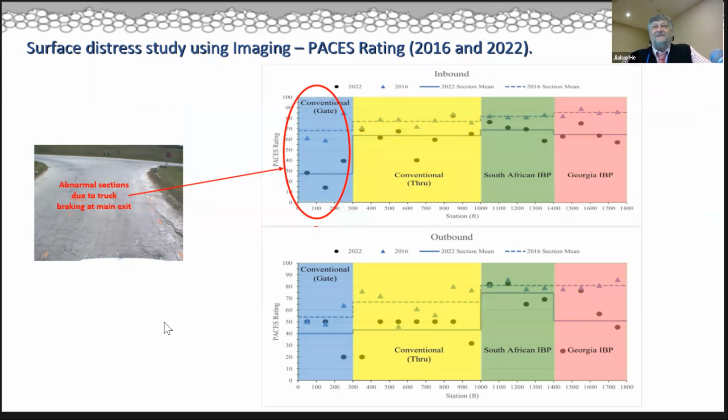We have a test section here, and other than the falling weight deflectometer that was put in, that was collected 6 years after it was first put in, we have no baseline data on surface distress, on rutting. We need to get a data set. And so as soon as I got involved in the project, we actually went out and did those measurements. And then we just did the follow-up set now 6 years later.